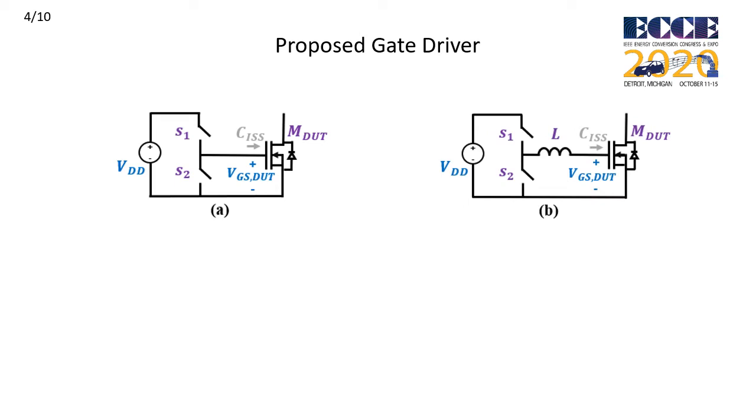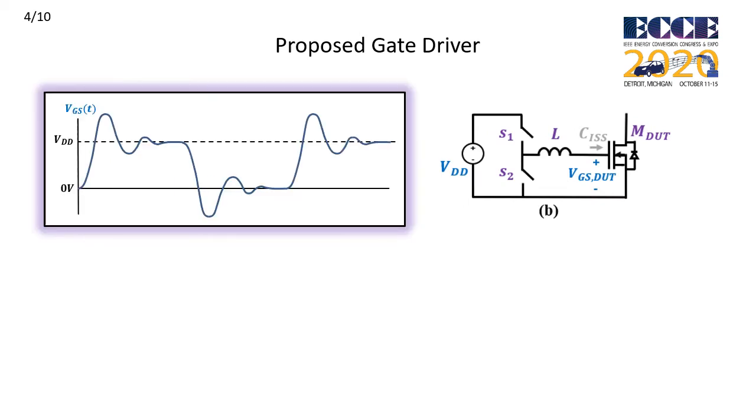Now, in this case, if we look at the gate voltage waveform, we see that we have exaggerated or accentuated the gate ringing. And we see that the extent of the ringing, or the percent overshoot, is a function of LC values and parasitic loss elements. So here, instead of burning off our CV² energy in an overdamped manner, we are using it to deliberately boost our gate voltage.